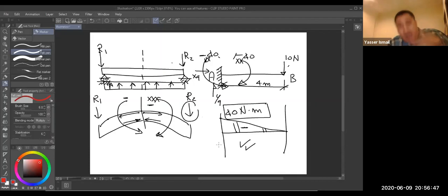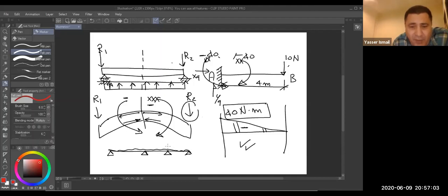So we put it up, because in any particular beams, especially a continuous beam like that, due to a particular load, the negative moment is always here. See guys, this is positive here, down, and negative here.